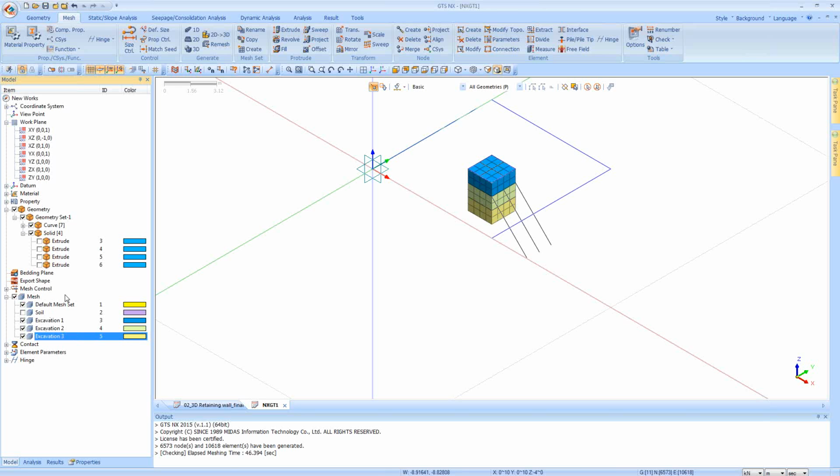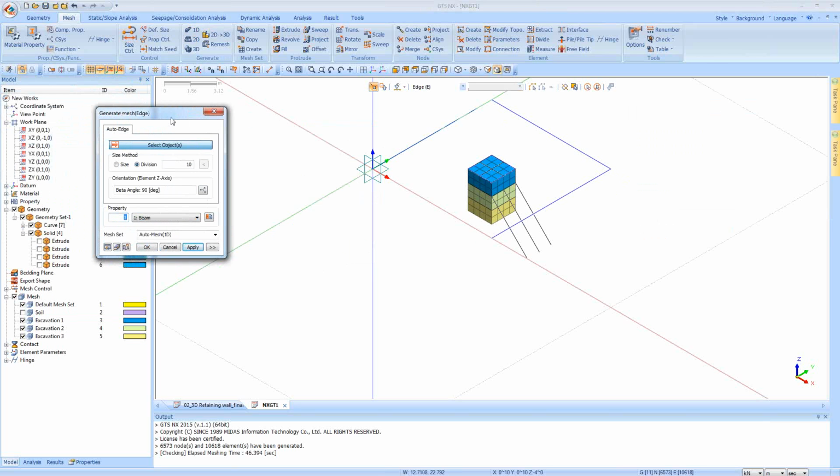Fine. So this is how you can define it. Now to generate the 1D mesh, you can just say 1D mesh. Select the object, say 1, 2, 3, give the number of size, beam. You can just name it as an anchor. So I'm just showing you how to create the 1D element, say apply.